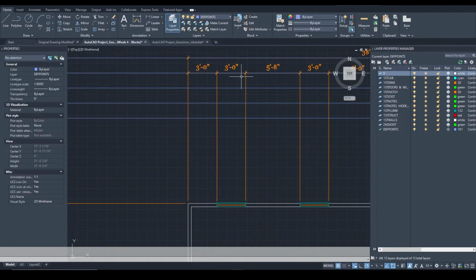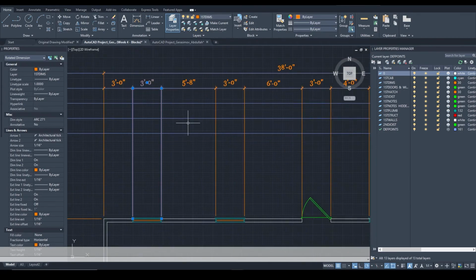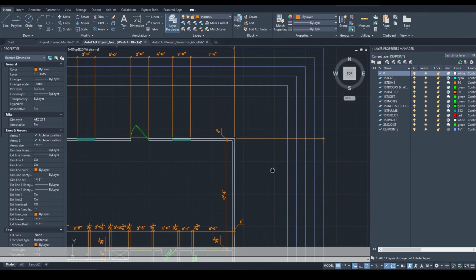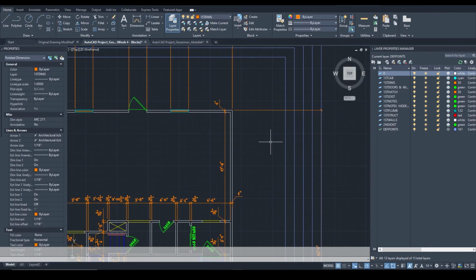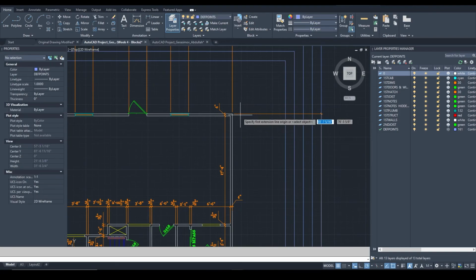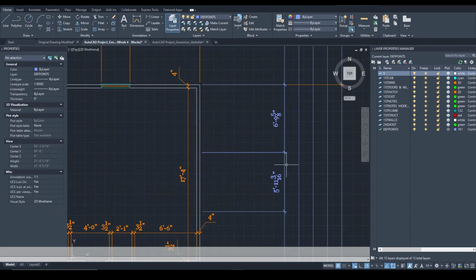However, in AutoCAD, unfortunately, once you create a dimension line, it's a single dimension line, and you have to create another one. However, there is a trick you can use if you want to create multiple dimension lines without having to press the same command again and again and try to align it with the previous dimension. Here's an example of what you can do, though this is not the most ideal. Let's say I dimension this portion. I press spacebar and I try to dimension this portion, and now I have to physically move this dimension line to this location. And there you go.